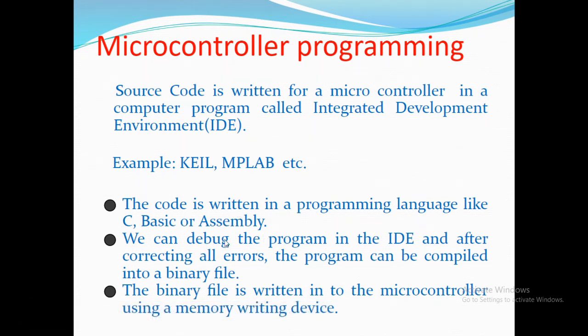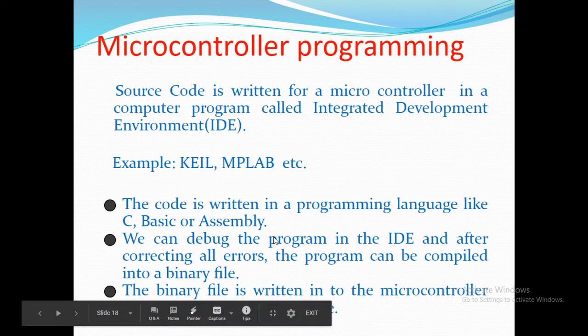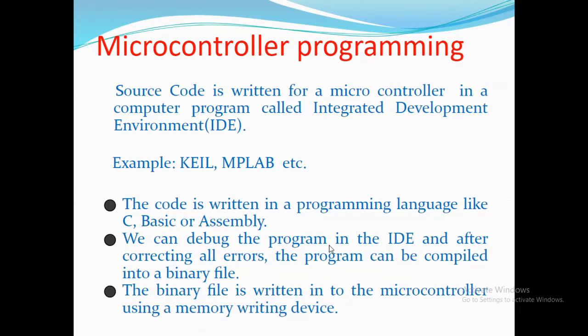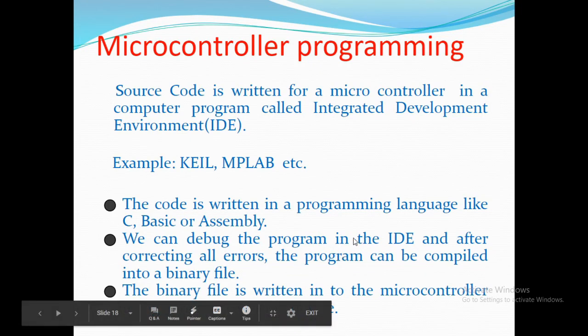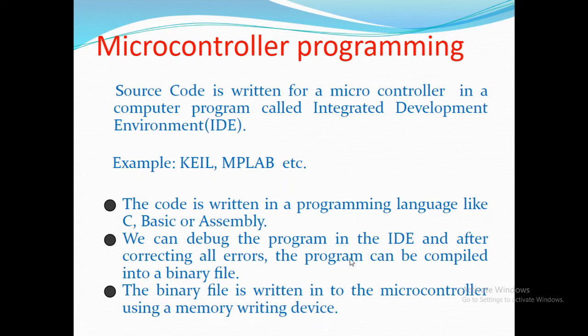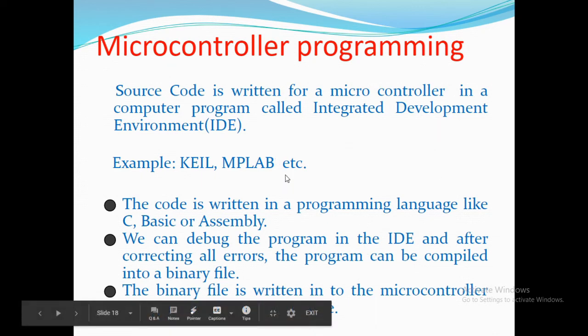After writing the code, you can run and debug the program in the IDE itself. After correcting all the errors, the program can be compiled into a binary file. The binary file can be written to the microcontroller using special memory writing devices.